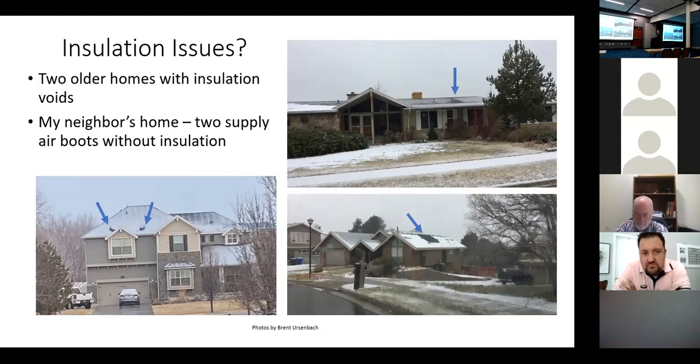How many attic installations do you see the HVAC guy run the flex, hook it to the boot, that it's nailed there, 12 inches, whatever, from the wall? How many do you see they insulate over the metal? None. Never, right? They just taped it. They tape to the boot, and so the back upper side of the boot is exposed to the attic.